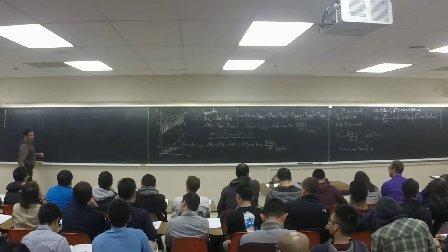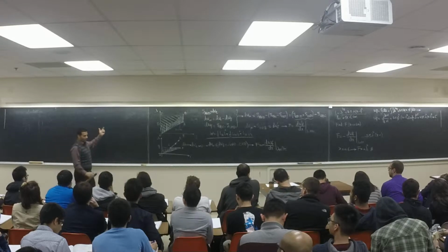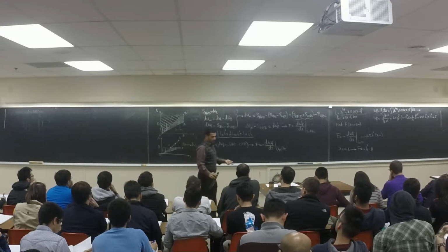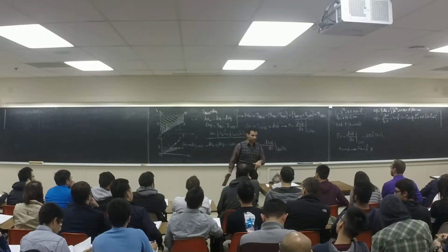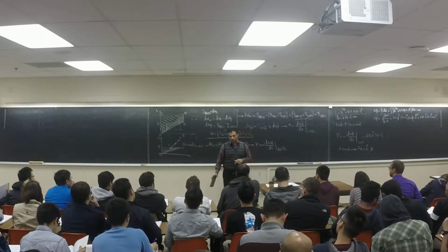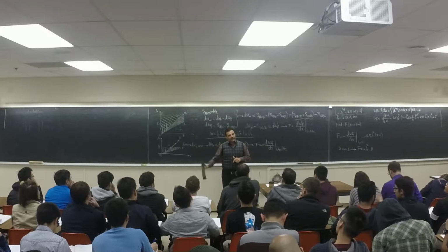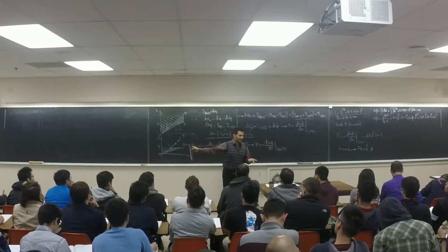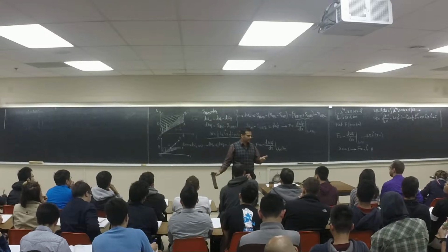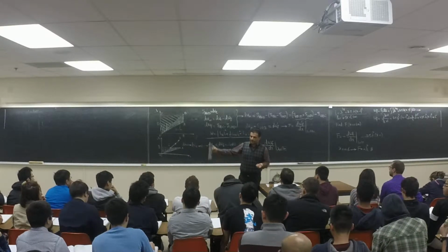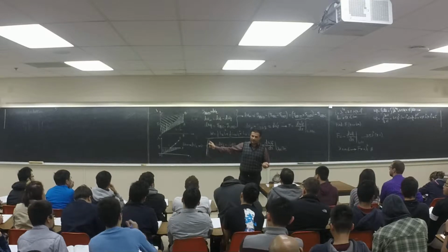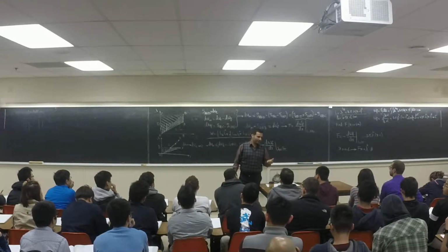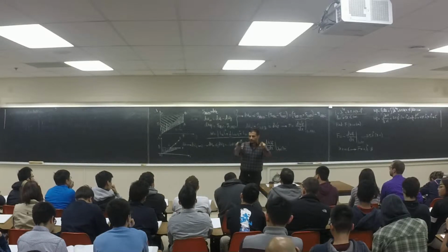The systems are not linear. Just to let you know, there are lots of people who design electrical motors, which have a torque. Torque is the next topic after the course we are going through. We're going to talk about it. They calculate all this energy or co-energy. Co-energy is a mathematical concept, it's not a physical concept. But they calculate all this co-energy and energy, either one, with finite element. When they use finite element, think about an electrical motor.